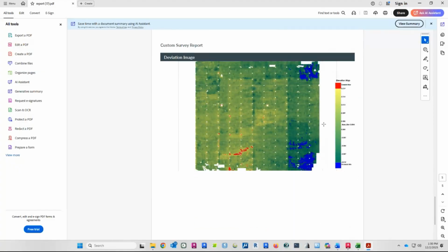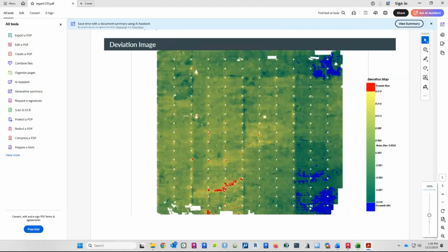And then this is a deviation map. Again, it'll be in the CAD file, but it's just an overall deviation. A lot of the floors only allow a certain amount of deviation, positive and negative, from your benchmark. And so here it will highlight automatically, hey, everything in blue is too low. You're 10 millimeters. You were only allowed 10 millimeters on this building, or 20 millimeters or something like that. So either side of that, it'll code it red or blue. If it needs to be cut, it's red, and if it needs to be filled, it's in blue. And the rest of it is just an undulation of the colors in between of the total deviation.